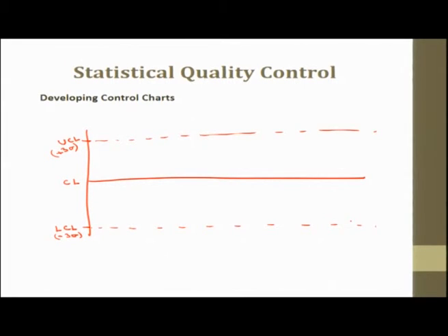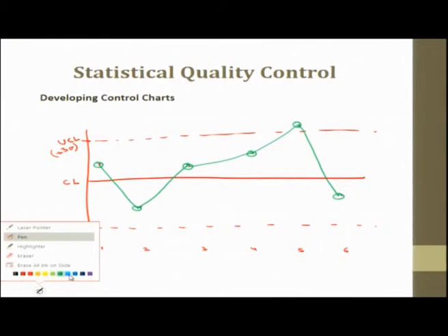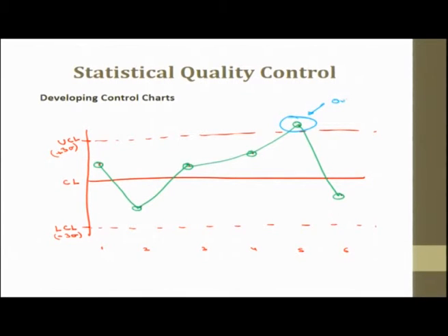So we have this line here, this is the upper control limit, this is the lower control limit. Then we will have our points here. This is the sample number, just a nominal scale 1, 2, 3, 4, 5, 6. Let me pick 6 points: 1, 2, 3, then 4 can be here, then 5 and then 6. I can draw a line here as well. You can see that there are 6 points, and the value number 5 is not in control, it is out of control.